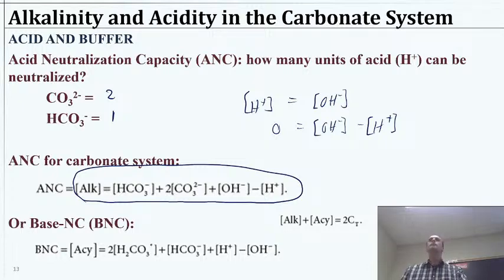Didn't we learn earlier that the left-hand side minus the right-hand side is defined as the alkalinity? We often solved for pH that way, to do a left-hand side minus right-hand side. Start with the electron neutrality, find the root to say left hand minus right hand equals 0, and solve for that in that manner. But we did derive the alkalinity in a similar manner by separating the strong base cations and the strong acid anions to one side and all the other species on the right side.